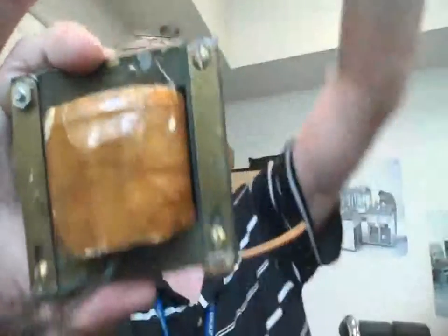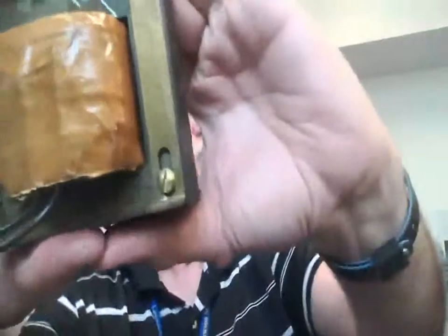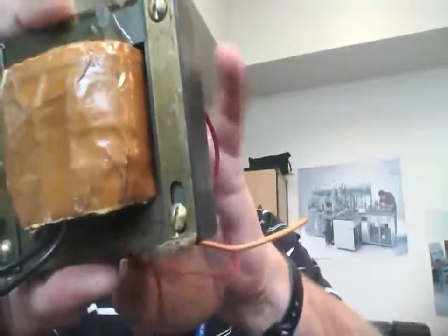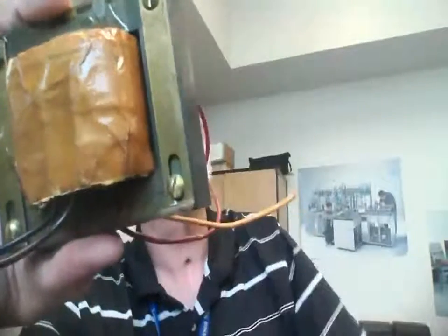So if I were to take these two coils of wire and use magnetic wire and wind them on top of each other, I would get a higher output. But I still wouldn't get maximum, because we have all this air where the magnetic fields go through. So we put metal in the center, and we call it the transformer's core. Instead of all these magnetic fields flying all the way out here, it concentrates them and makes sure almost over 90% of the field generated in the primary gets into the secondary.